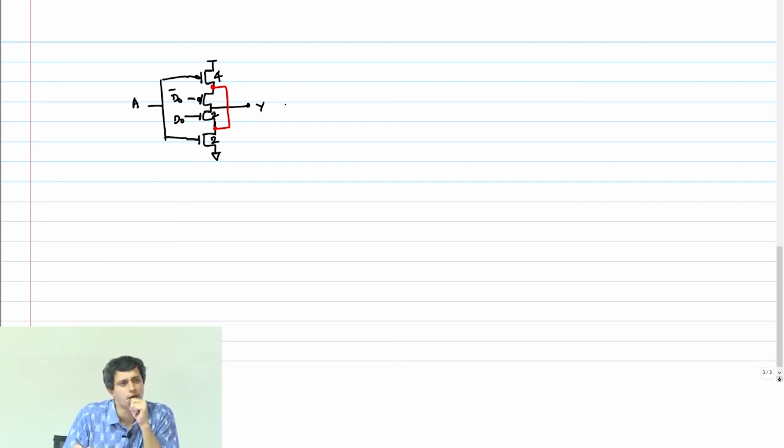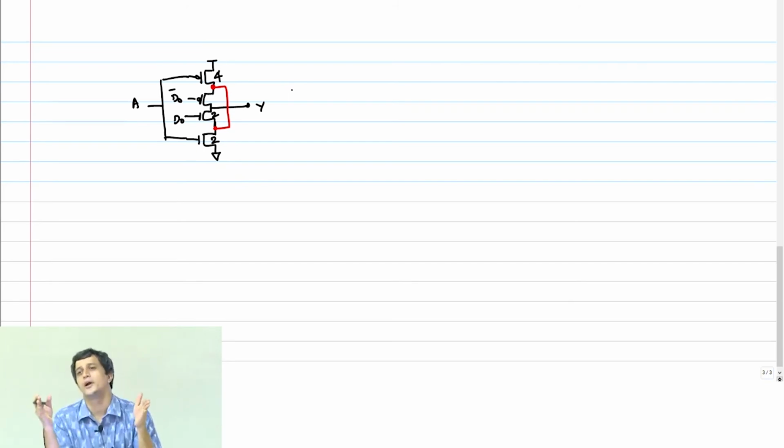What about that 2 there? Should that PMOS be 4? Technically, it's not necessary because the NMOS and PMOS are actually conducting together. Even though the NMOS cannot pass a logic 1 completely, for most of the time it's going to allow conduction. Until it goes to VDD minus VT, the NMOS is also going to conduct along with the PMOS.